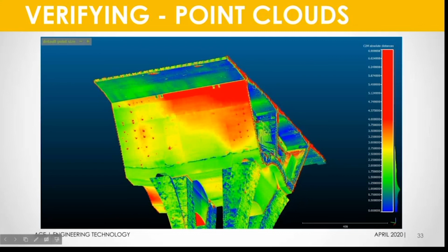So in this case, this is a bridge structure about 100 feet wide, about 90 feet in the air. And all of the concrete formwork that's supporting this, right, believe it or not, when you pour concrete into formwork, that formwork does move. Now, mind you, it may only be fractions of an inch, but in some projects, you can have very tight tolerances where fractions of an inch really add up and matter.